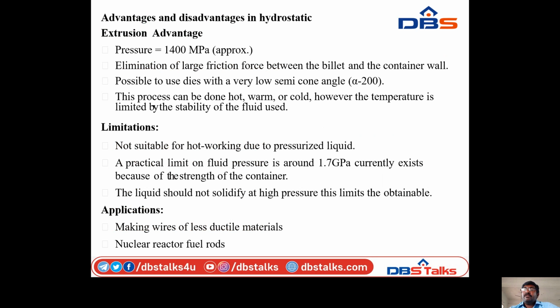Next, advantages and disadvantages of hydrostatic extrusion. Advantages: pressure, which is equal to approximately 400 megapascal. The elimination of large frictional force between the billet and the container wall. It's possible to use dies with a very low semi-cone edge angle, alpha, for example, alpha equal to 20 degrees.